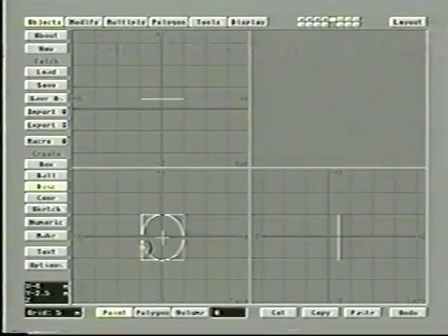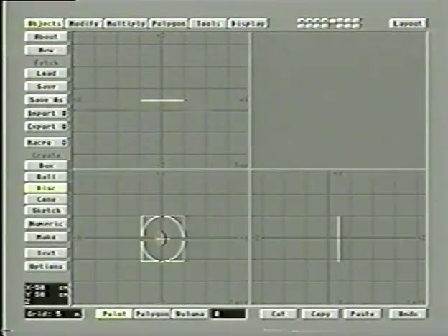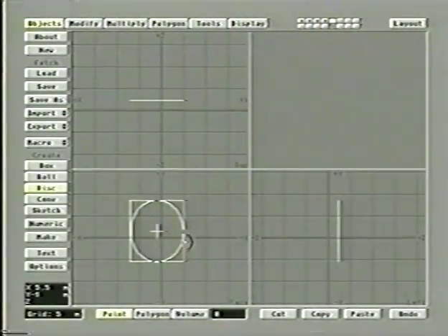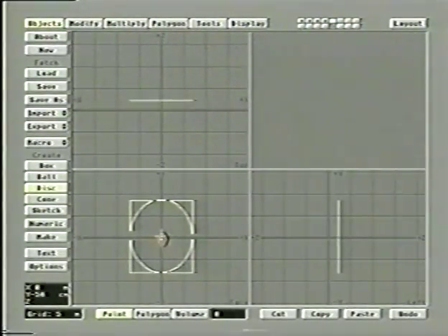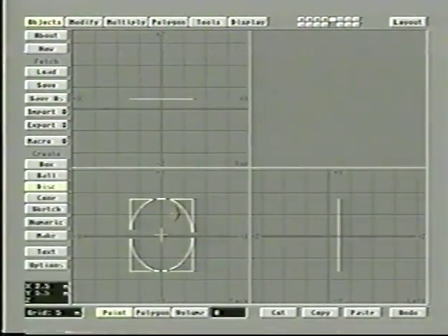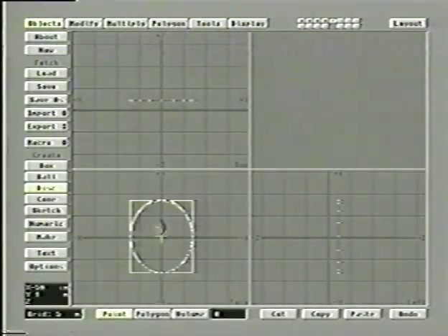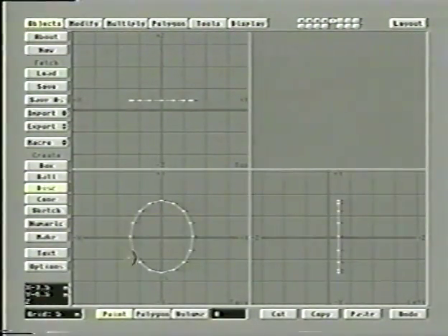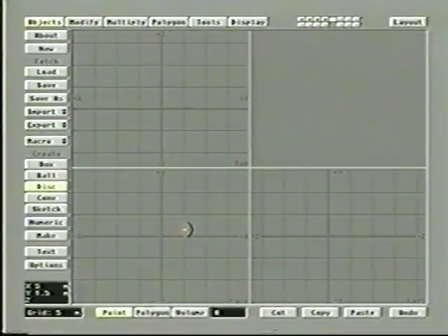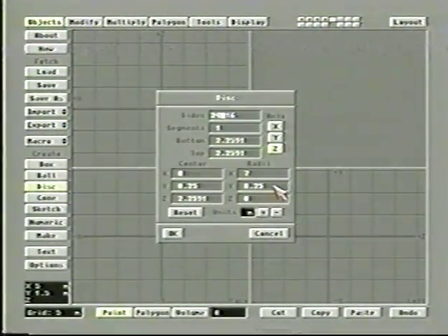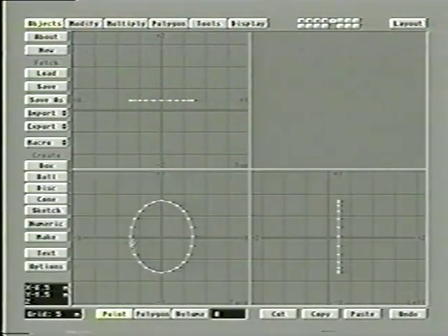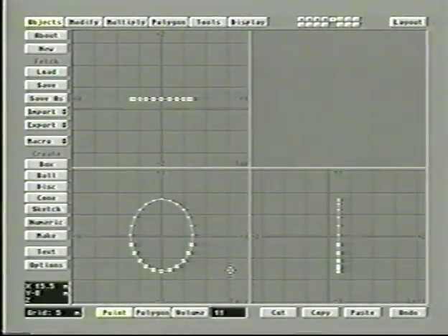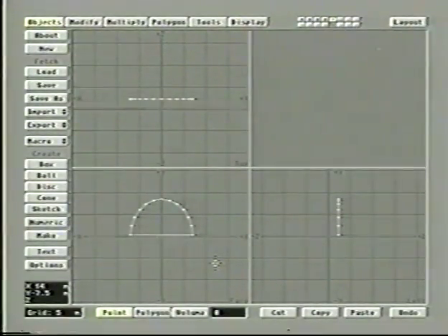And so now we've got a tunnel that's about 15 feet high, 30 feet across. Let's make it a little bigger than that even. That'll work. Something like that. Now what we want to do is make this flat shape. And maybe I want a few more. Let me just undo it because I can see it's only doing 16 sides around. Let me just go to my numeric option and enter 24 for sides, just so it's a little rounder. Now again, we pick the bottom points, cut them away. There we go. Now, here's our basic tunnel shape.